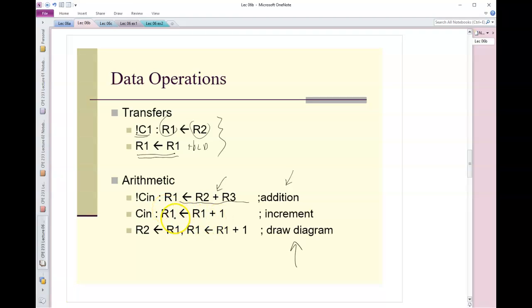This is a standard operation here that looks like addition, right? Under some condition here, I don't know. But if you think about it, this is actually what a counter does, and this is a typical increment operation. So technically I could throw a ripple carry adder in here and model it like that, but it's better that I notice it's simply doing an increment and use a counter to implement this RTL.